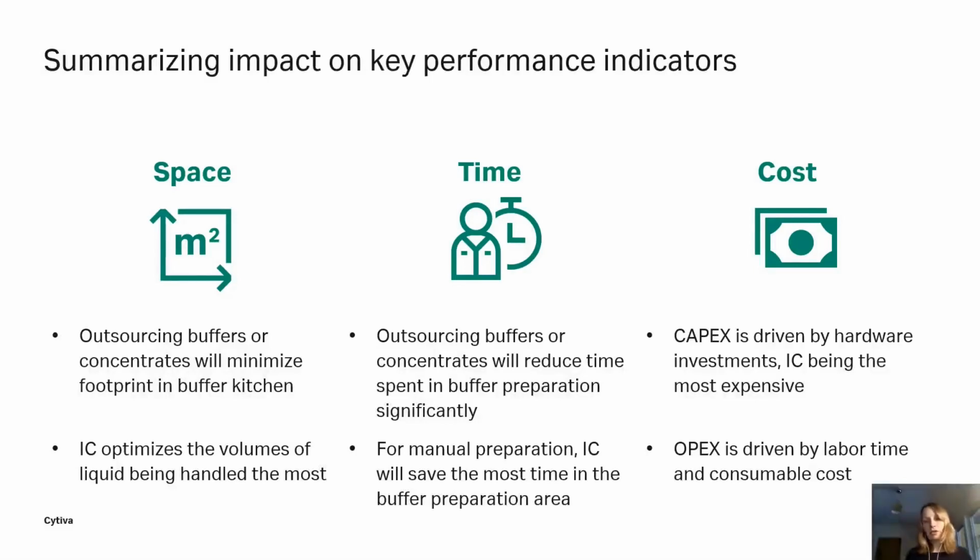If we look at cost, CapEx is driven by hardware, where inline conditioning being the most expensive, and OpEx is driven by labor time and consumable cost. Also do remember that we used a conservative process that converted 12 buffers to 10 stock solutions. So for other processes, or if you consider several processes at the same time, difference between, for example, inline conditioning and inline dilution might be higher.